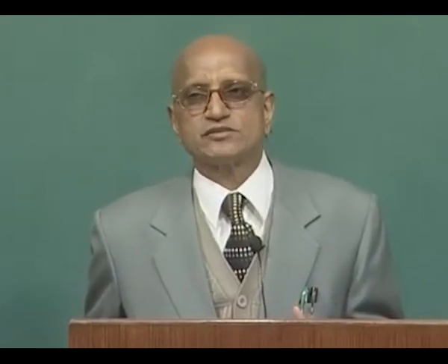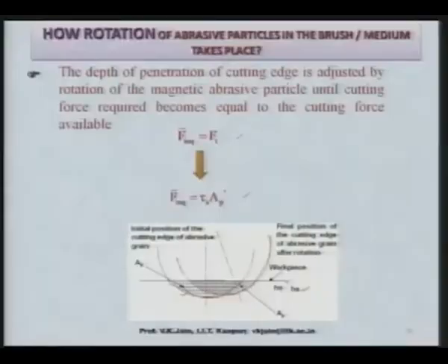axial force or the cutting force required will definitely be smaller to remove the material in the form of a chip, and this H s dash gets adjusted till the abrasive particle is capable of moving further. So, this is how it attains the condition when a very large normal force is acting, but still it rotates and attains the condition that it can remove the material in the form of a microchip. And the whole of this analysis has been carried out using the finite element method by Dr. S.C. Jaiswal of IIT Kanpur.